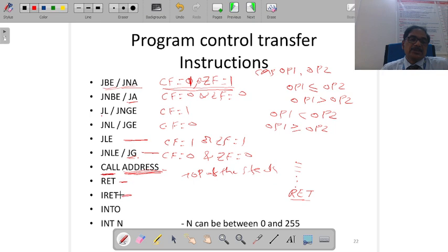The last instruction in the interrupt routine is IRET, that is, return from interrupt. Whenever an interrupt sequence is to be executed, the processor will stop the current sequence, the address of the next instruction will be stored on the top of the stack, and it is going to deviate to the interrupt routine.